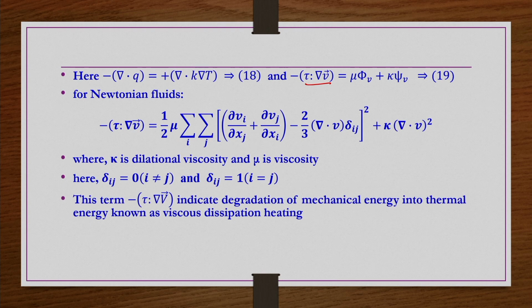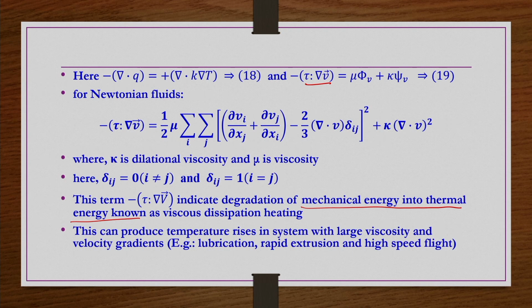So, this term indicates degradation of mechanical energy into thermal energy, which is known as the viscous dissipation heating, or energy due to the viscous dissipation. And this usually has importance when we have highly viscous fluids which are moving at high velocity. Usually highly viscous fluids do not move at high velocities in general. So, in most applications the contribution of this viscous dissipation is very small. However, there are many cases where it is also included.